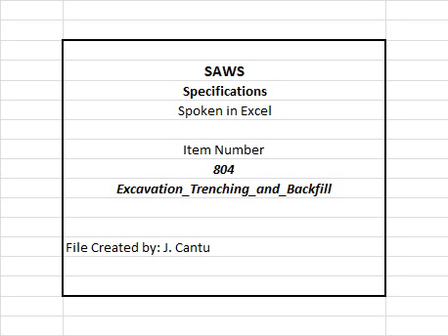4. Temporary street striping may also be required. 5. This surface must be removed prior to final asphalting. G. All street work shall be done in accordance with the latest City of San Antonio Public Works, or other city as applicable, construction specifications. H. Included in this requirement is replacement of any curbs or sidewalks damaged or removed during the construction. I. No separate payment for the surface restoration is permitted. The cost for this work must be included in the appropriate bid item.